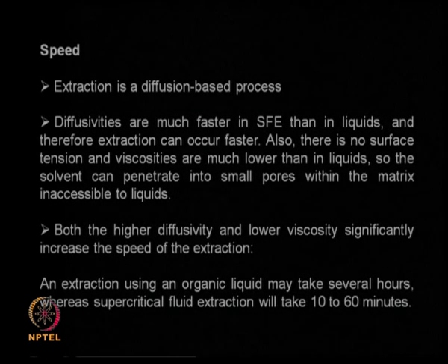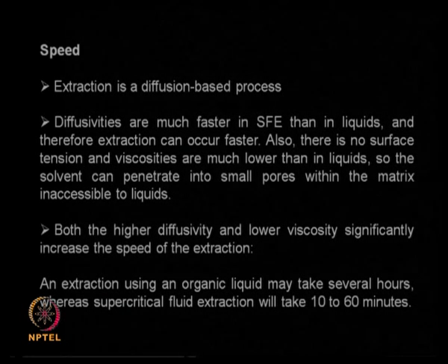Speed is very fast because it is based on diffusion, and as I showed a few slides back, the diffusion coefficients are very high as against the diffusion coefficient of a liquid solvent. There is no surface tension, and viscosities are much lower than in liquids, almost close to gas.